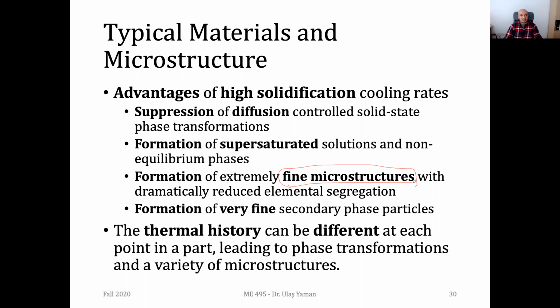And another issue about microstructure is that by adjusting again these parameters, the solidification settings, you can have different microstructures in one region and another type of microstructure in the second part of, let's say, the same part, which is a nice property again. And this is not possible with any other additive manufacturing or conventional manufacturing operation or casting operations. You can always have various microstructures in your part.